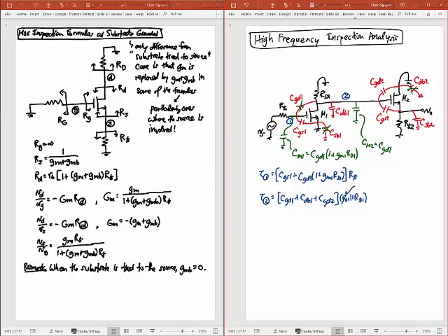Okay? And so tau 3, I'm now looking for all the capacitance at node 3, which is this node here. Let me write. So that's at my output node 3. And so all that capacitance is just going to be one capacitor. That's just CSB2.